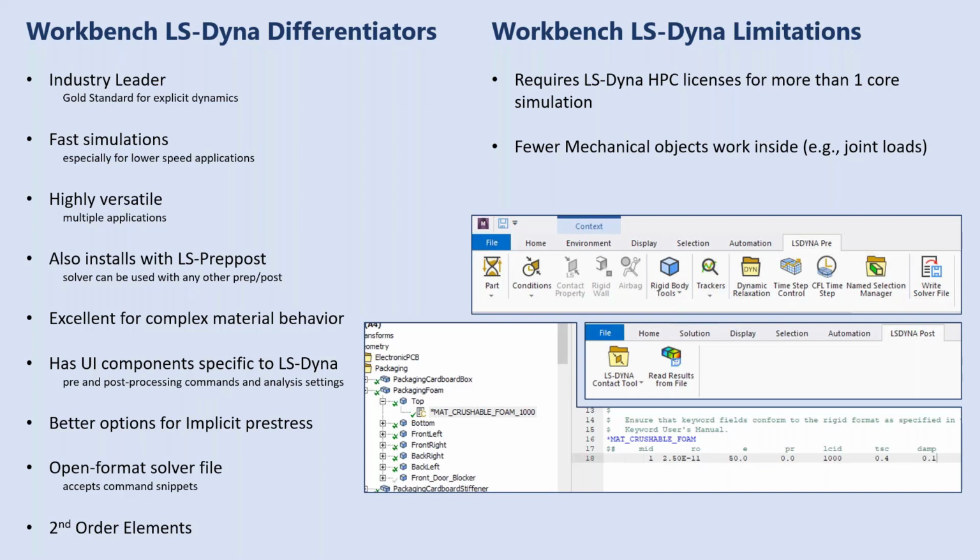It's really excellent for simulating complex material behavior, large strain simulations. It has some UI components that are really specific to LS-DYNA simulation, where you get essentially different contextual tabs in the ribbon with different commands when you run this tool, as compared to, for instance, Explicit Dynamics, which really uses the same commands, same boundary conditions as any structural simulation in Workbench.